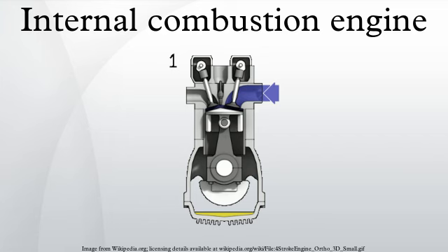An example of this type of motor is the Wärtsilä-Sulzer RTA96-C turbocharged two-stroke diesel as used in large container ships. It is the most efficient and powerful internal combustion engine in the world with over 50% thermal efficiency. For comparison, the most efficient small four-stroke motors are around 43% thermal efficiency. Size is an advantage for efficiency due to the increase in the ratio of volume to surface area.